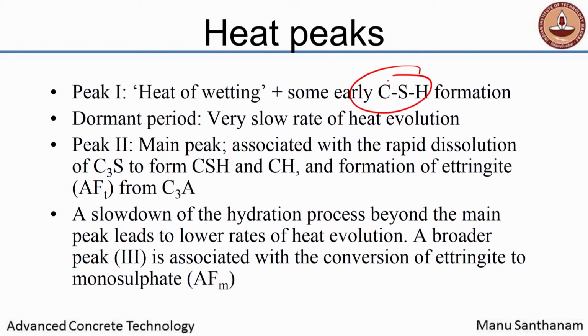Of water and cement. If there is a difference in temperature of water and cement, that may release some heat. Yes. What else? Okay, that is the reaction heat. So, this early CSH formation is causing some reaction-related heat.